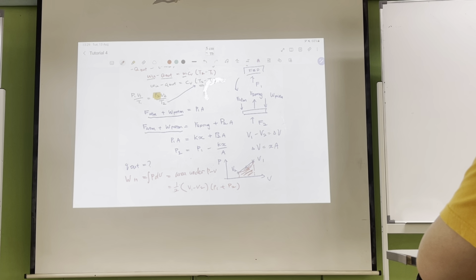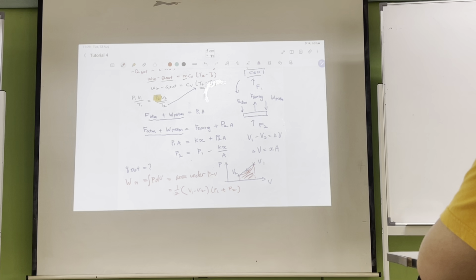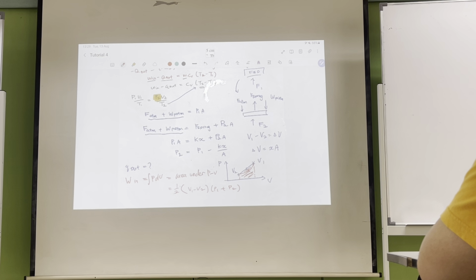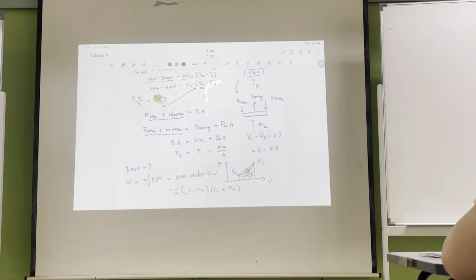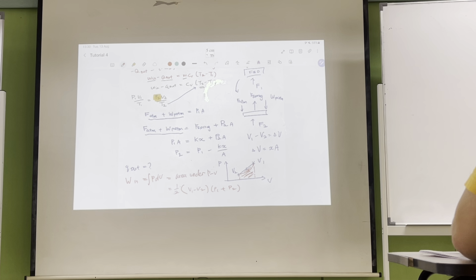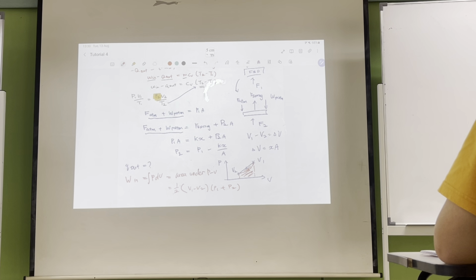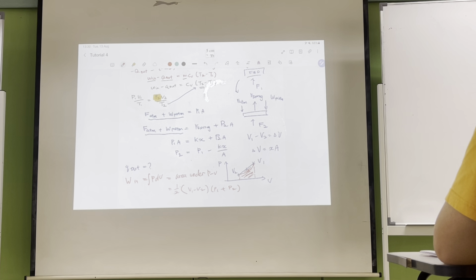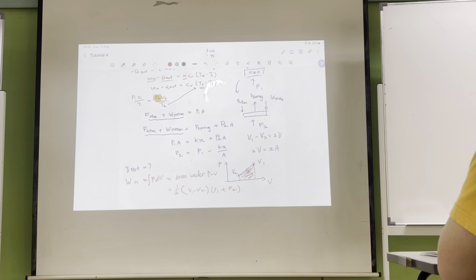Okay, so this is actually one very important thing. You will see it in some of the past year questions as well. Whenever you have a spring, it will be the easiest for you to find the boundary work, because you can just draw the PV diagram, and based on the graph you can find the boundary work from there. Then you don't need to think too much about it. If there's no spring, then using area under the graph will be a bit tricky because you get a curve, so the area under the graph is harder to find. And like I said, I won't ask you to do integration, so those cases won't happen. Then you will need another method to find it. With a spring, then yes, you just need the area under the graph.